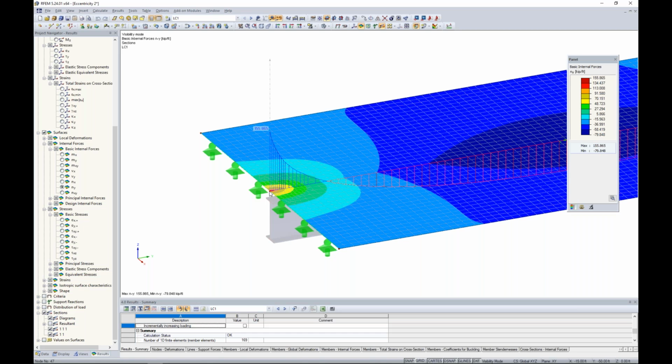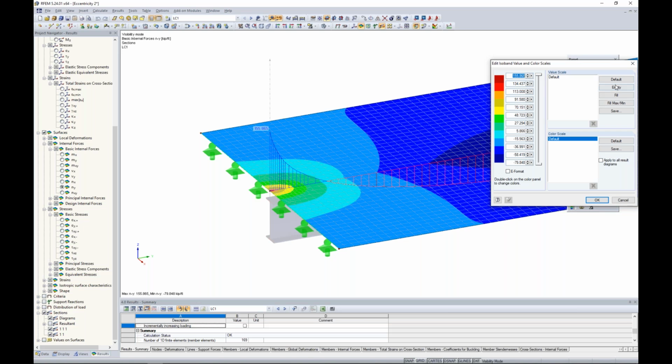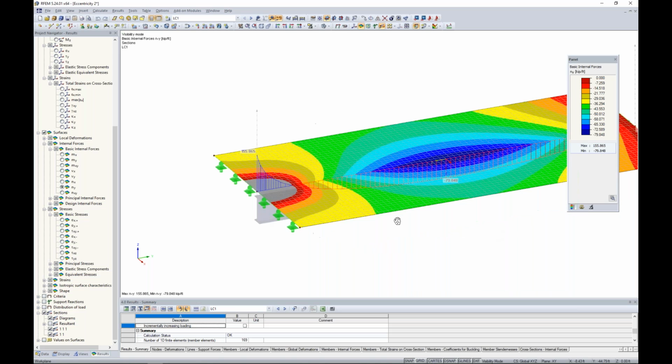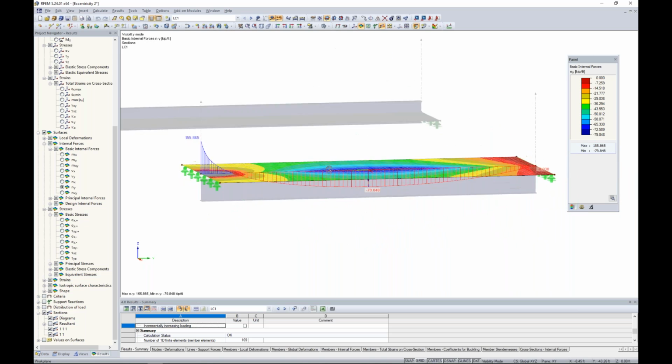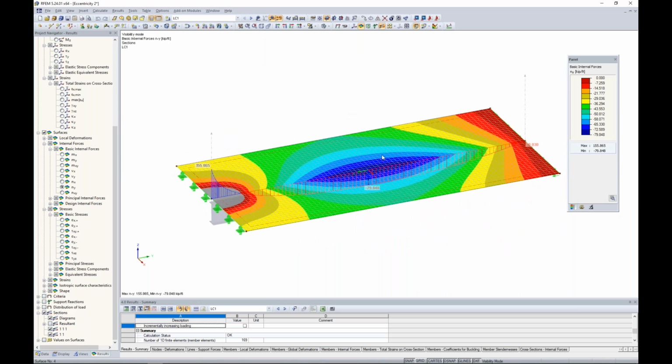So we could probably use an average region, maybe rigid links, to take care of that. In our control panel, maybe we completely take out tension and adjust this to only look at the compression forces. And it's really as we'd expect. We want this slab element to take those compression forces from this applied area load.